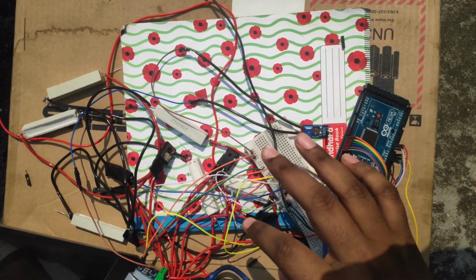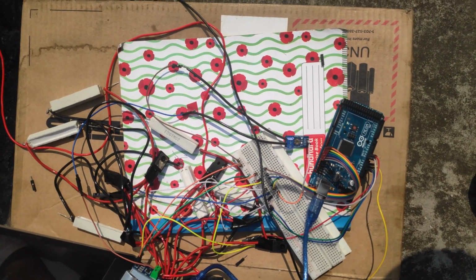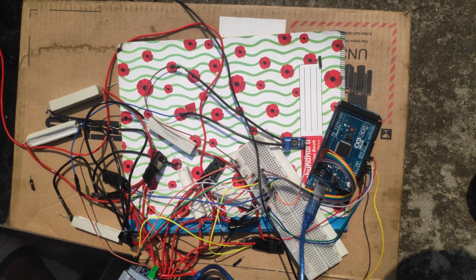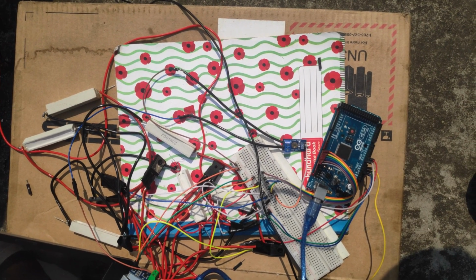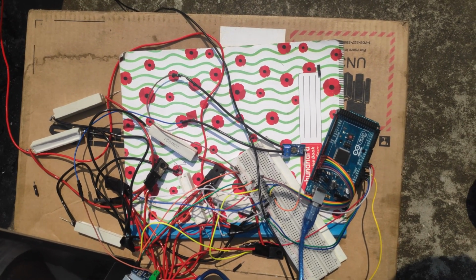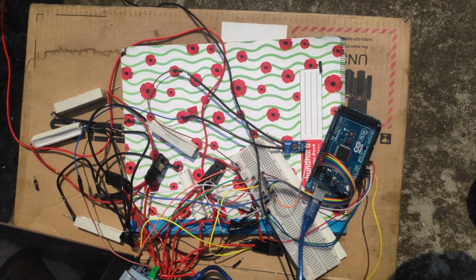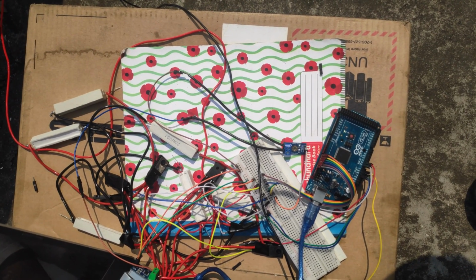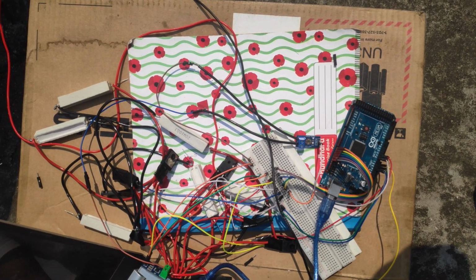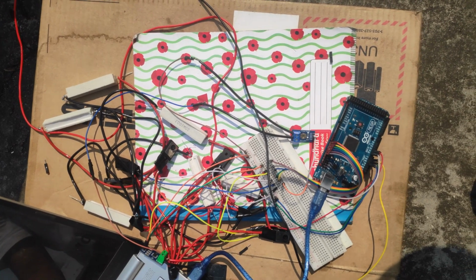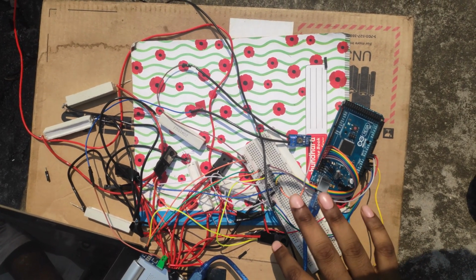Here we have ceramic resistances. Why have we taken ceramic resistances? Because they have a high power handling capability. The resistance values that we have taken are 1, 5, 10, 12, 16 and 100 ohm. We have taken 6 points, and by switching MOSFET gates over and over, we can take up to 64 sample data.